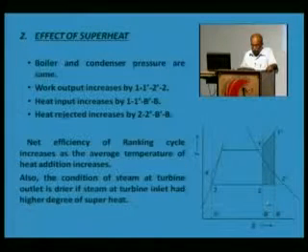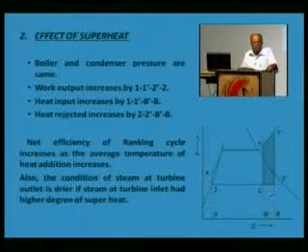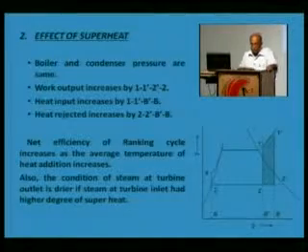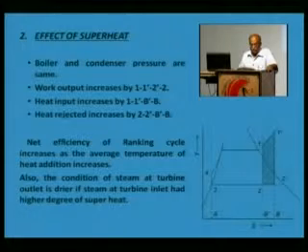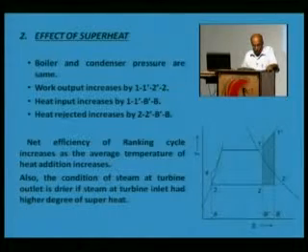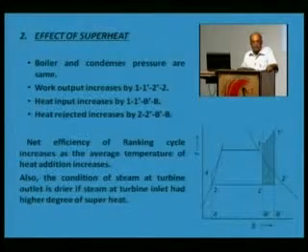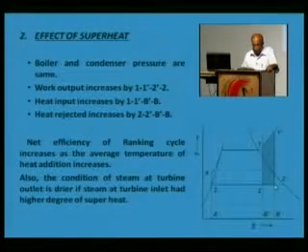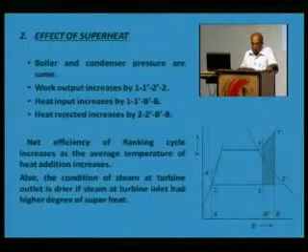The ratio of the two areas, the rate of increase of work is more than the heat that is being lost in the condenser, and therefore, the efficiency would increase if the temperature of superheated steam at inlet to the turbine increases. So, the net power of the plant will also increase and the efficiency will also increase. The steam will be drier at the end of the expansion process, and that would improve the working of the turbine also. So, we wish that the temperature of steam should be as high as possible.